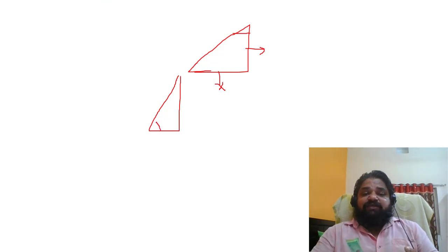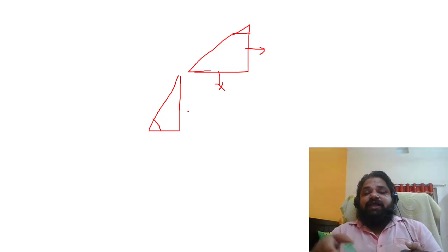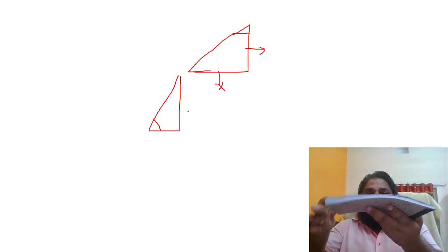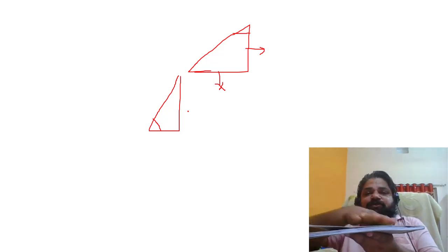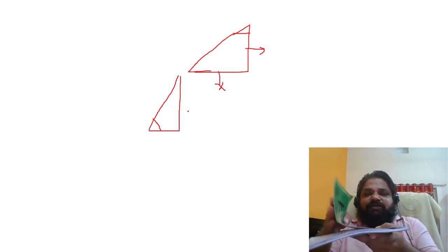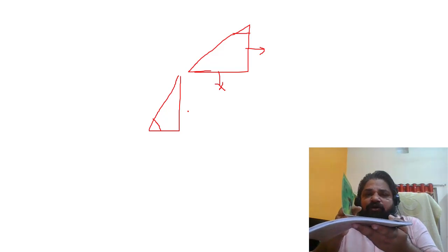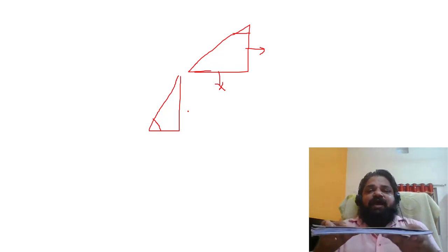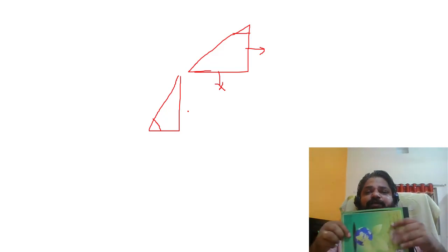That means now sigma x, sigma y and tau xy are a combination, and that combination I am now making flat. Instead of 90 degrees, I am making it flat. The plane which contains sigma x and tau in the vertical plane, similarly the horizontal plane keeps sigma y and the tau. Now I am opening the sigma x, sigma y, everything on a single plane.